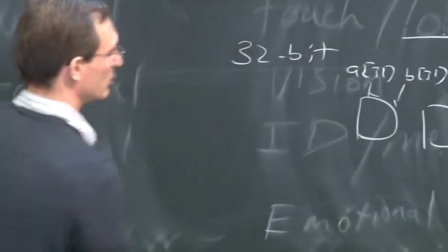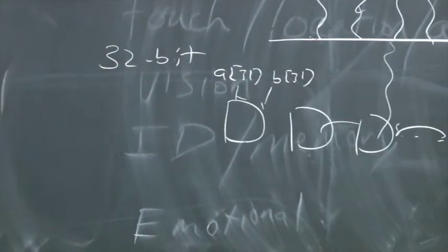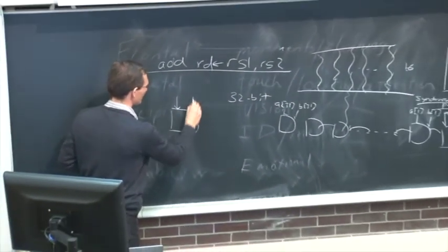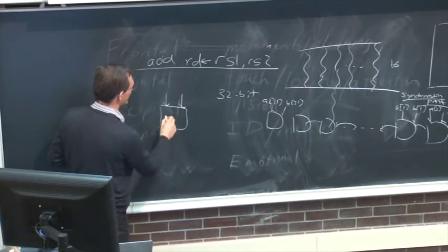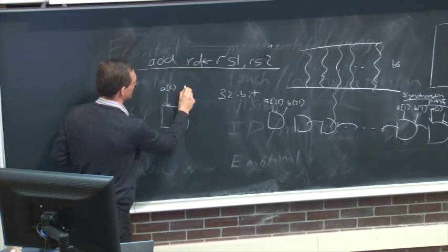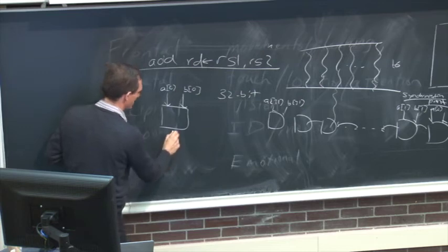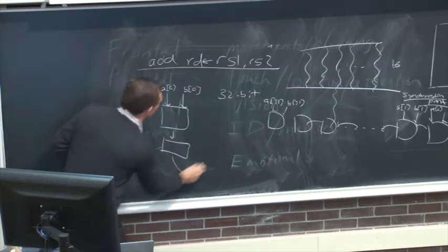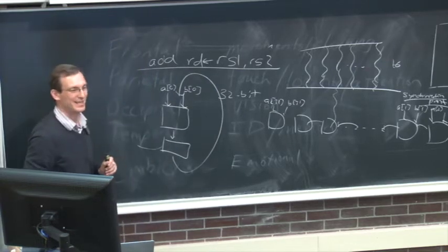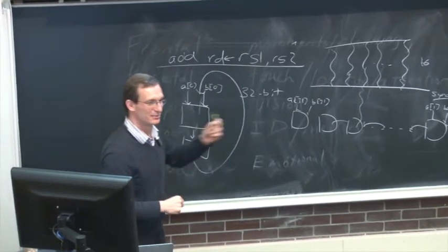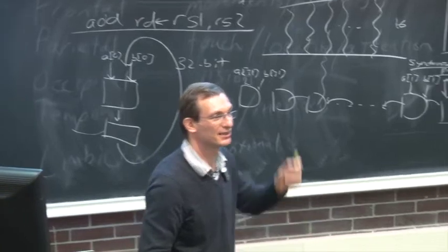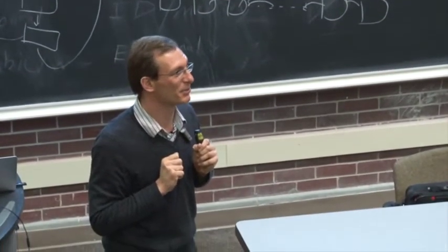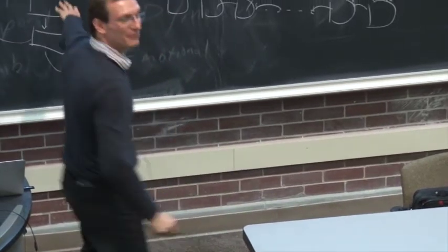Bit serial adder, you don't have 32 of these adders. You have only one, right? And what happens is you start with A0, B0, feed it, latch the result, and then shift it. And then feed it back. Make sense? It's bit by bit. Every cycle, you add one bit from each value. It's simple, right? Even that's a trade-off.